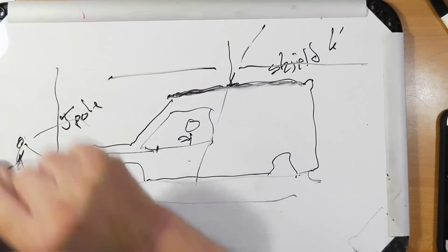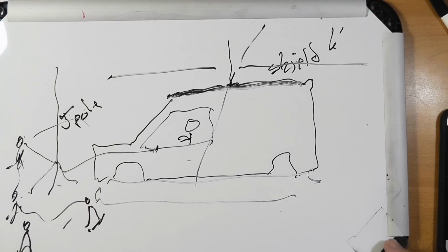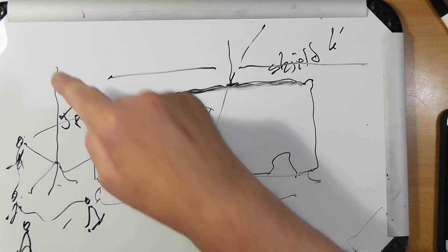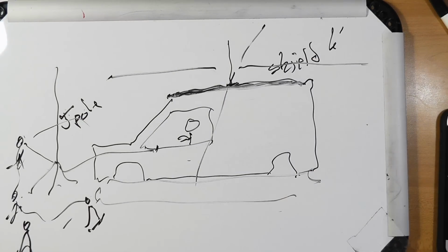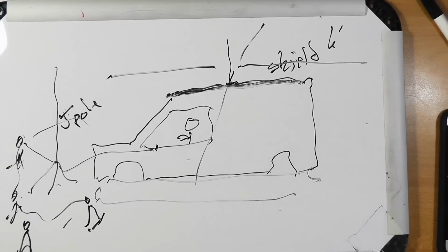This is a very common scenario at an event. And if you can set that J-pole antenna up on a tripod, put sandbags over this so the wind doesn't knock it over. Rather than use the antenna there, use the J-pole. They have about the same amount of gain, actually. This is a half-wave end-fed dipole. This is a quarter-wave vertical against a ground plane. Okay? So that should help answer the questions.